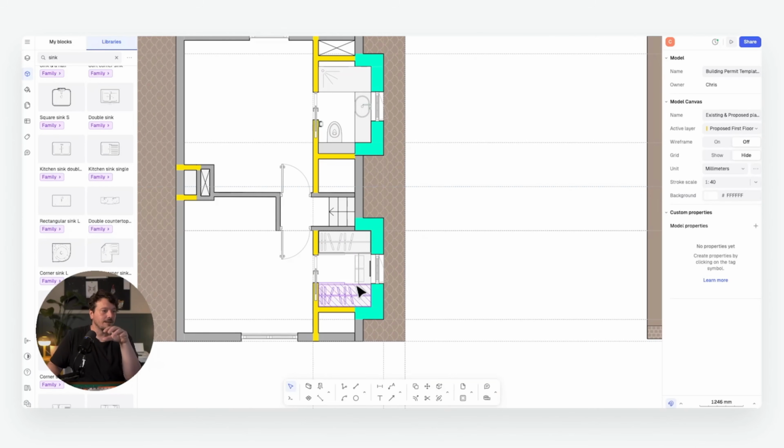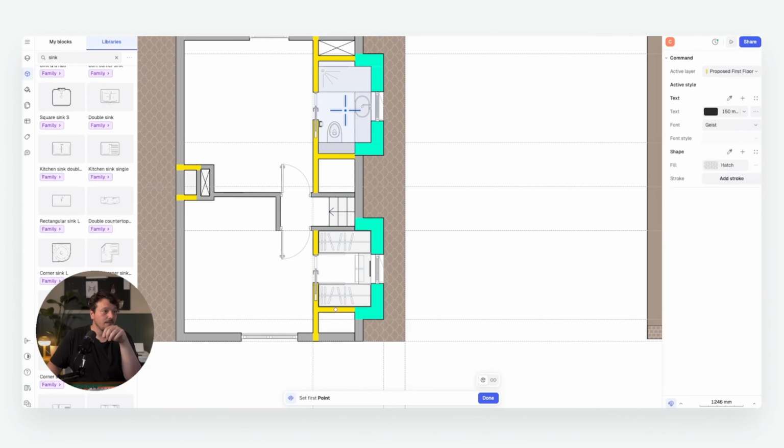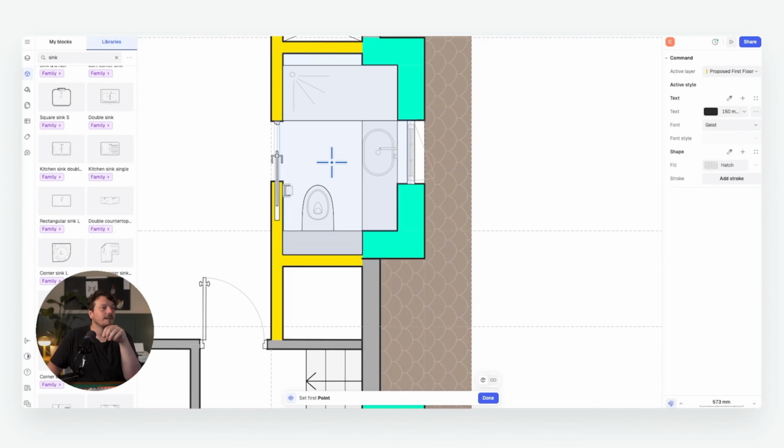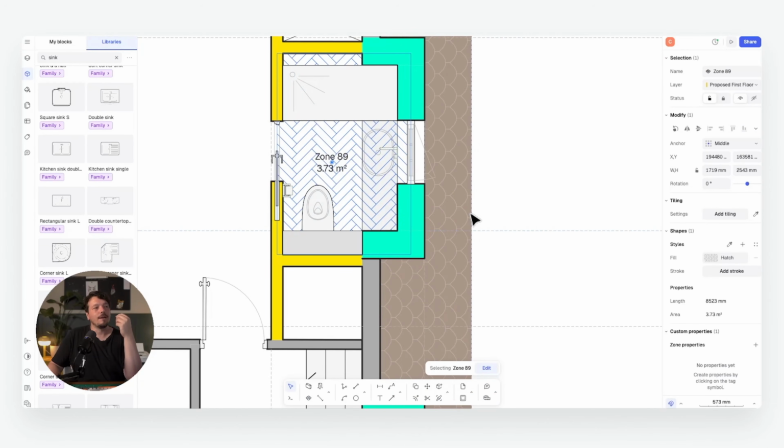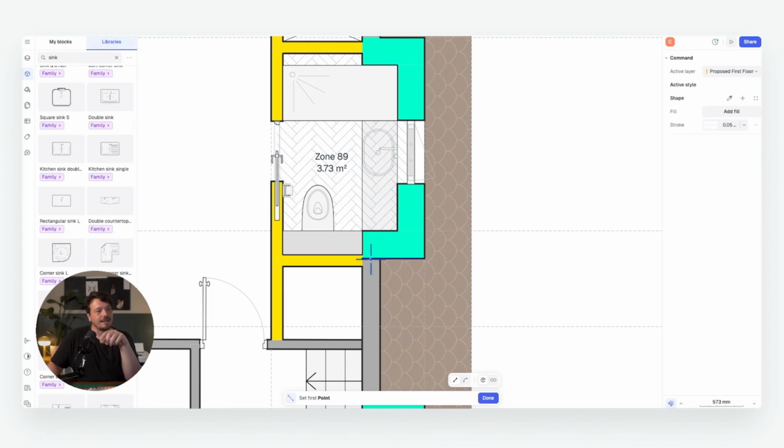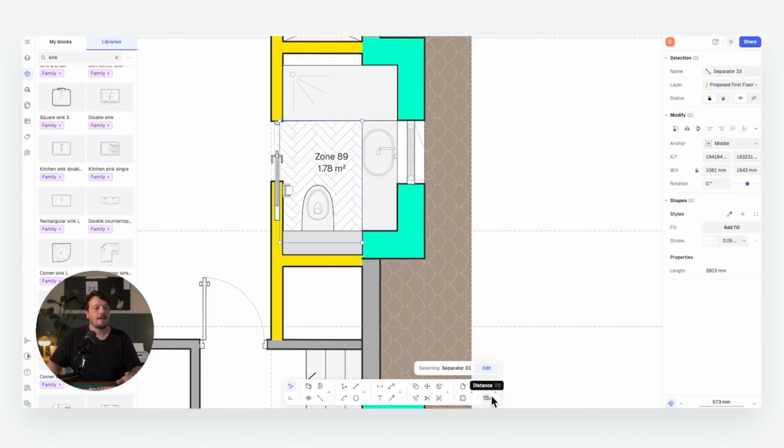And again, just like all of these things, I can add in a zone. So you'll see here, for example, because the zone is reading the walls, it tries to fill the whole space. Whereas you can use a zone divider tool, which is just down here, and you can add a division to that space, and that means it basically segments that space and no longer sees it as the full element, which means that the pattern will fill where we want it to be.